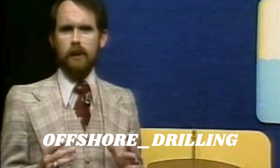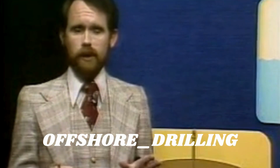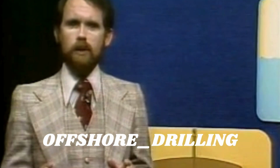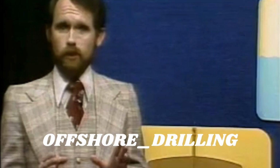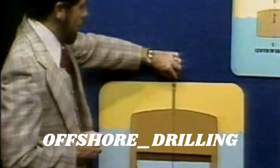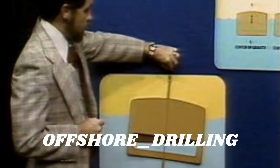In discussing the position of a vessel's center of gravity, we have assumed that everything in the vessel was fixed in position within the vessel. For all solid materials, this is true, unless the materials are free to roll around with the motion of the vessel. It should be obvious that where we have partially filled tanks containing water or fuel, there will be a movement of this liquid as the vessel or rig is inclined.